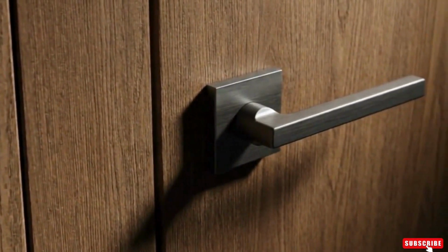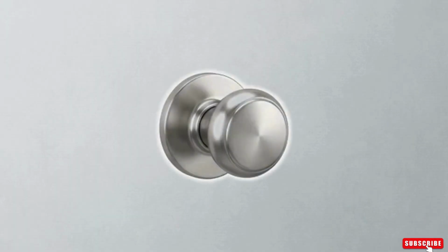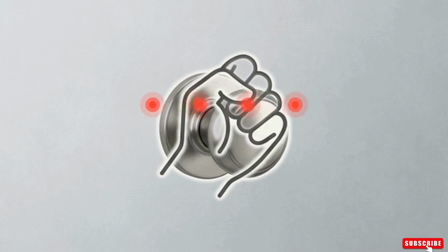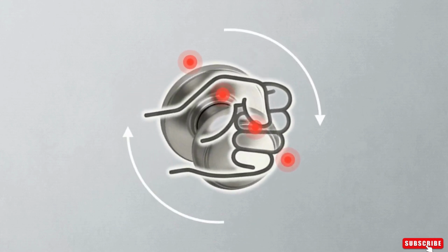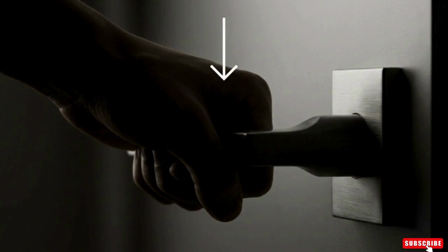Once the macro spatial layout is resolved, optimization scales down to the micro interaction point, the door hardware. Operating a traditional round knob requires tight, sustained grip strength combined with a simultaneous twisting rotation of the wrist. A lever handle functions through a single downward push. The mechanical advantage of the lever determines its accessibility. This vector diagram compares the forces.